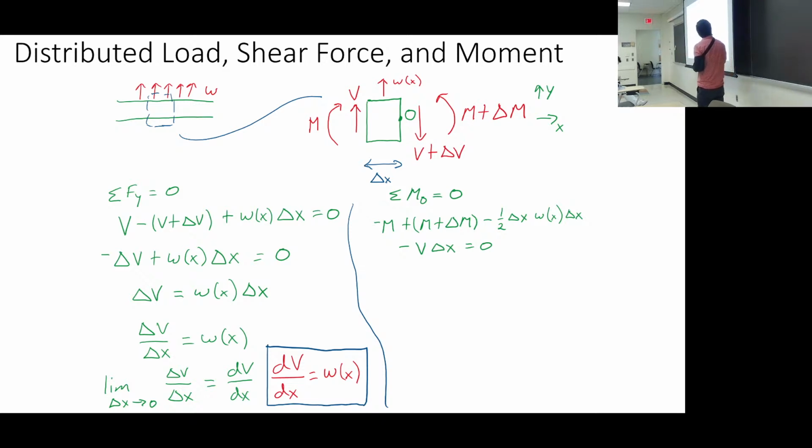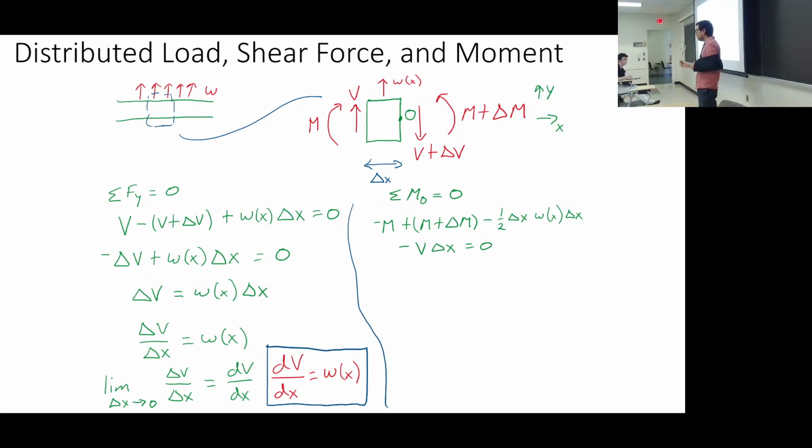Remember, a moment doesn't care. It's like you take this screwdriver, slam it into the beam, and twist. That torque or moment applies to the whole system, wherever you put it. But if I say I'm placing a force at a given location relative to the rest of the system, then I have to keep track of where it's being applied.